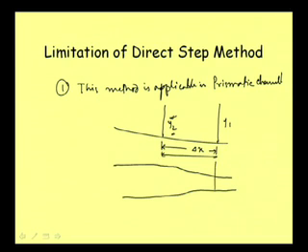When we have y1 at this section, section 1, and then we took y2 because we do not know, we thought that y2 may be somewhere here, and that is why we thought that this part is prismatic, more or less prismatic, and thinking in that line, we took the y2 value and started computing the delta x. But when we finally computed the value of delta x, we find that delta x is coming here, and we do not have any control on that.